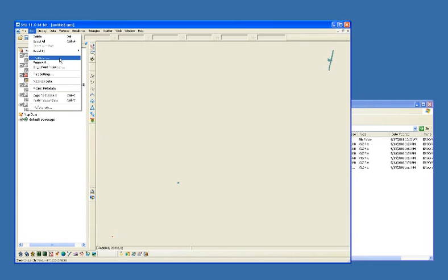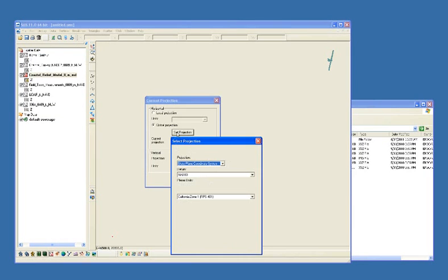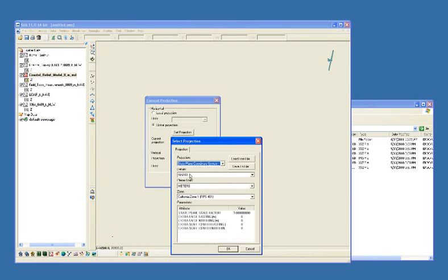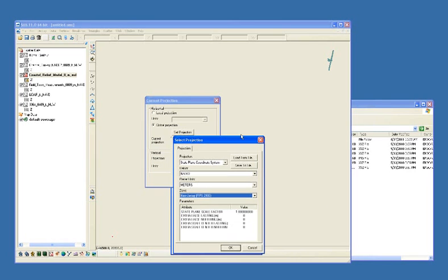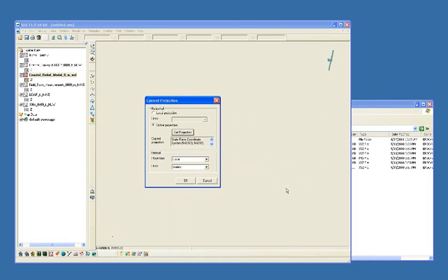So you have made a conscious decision that for this project, I'm going to be working in, and I'll set the projection, state plane, NAD 83, and I'll switch this to New Jersey. Let me find it. Here it is. And make sure that it's in meters. All right, and so click OK.